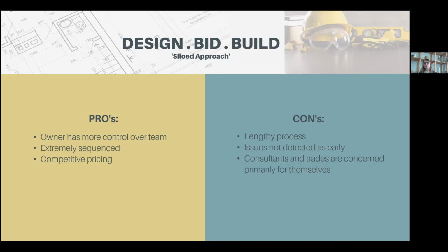The cons are that it's a lengthy process. Because you finish all of the design and then you have to do the tender and then you have to do the build, nothing overlaps with each other. You don't have a builder who's going to take out a permit before the design is done, because you don't know who the builder is until after the design is done. Issues are not detected as early.